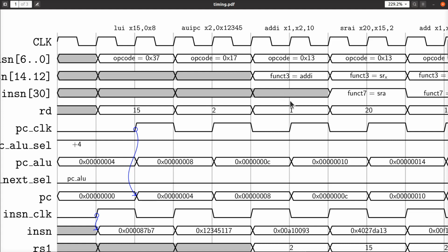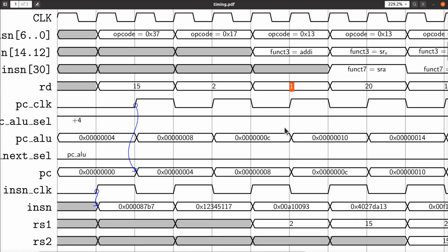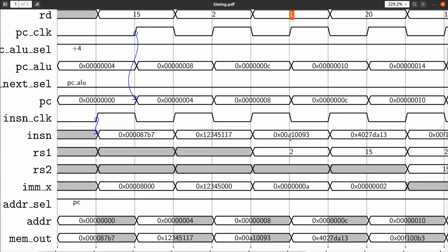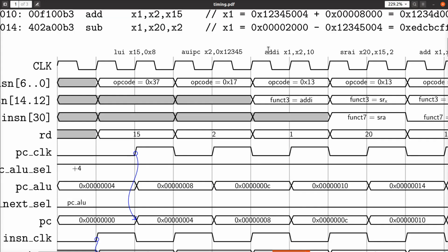So what happens then down there? Okay, so again, we have the X1 register in the instruction, and the bits that represent the RD field will have the 1 in it, so I show that in here. We already talked about the program counter clock. We've already talked about how the instructions are fetched and everything else. This all lines up and matches in all the other instructions. Remember, the add immediate has a destination register, it has an RS1 field, and it has an immediate operand, okay?